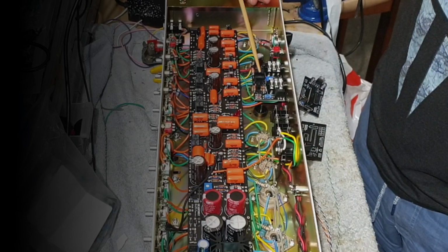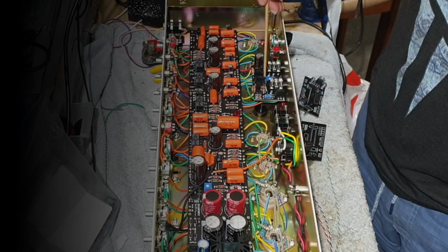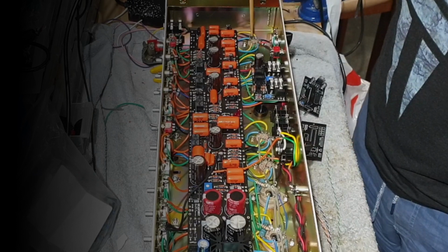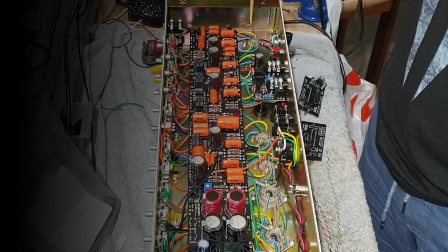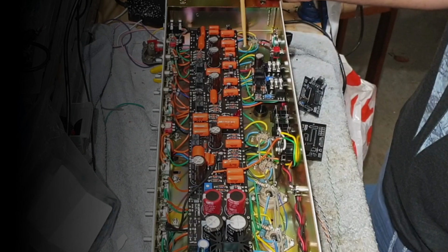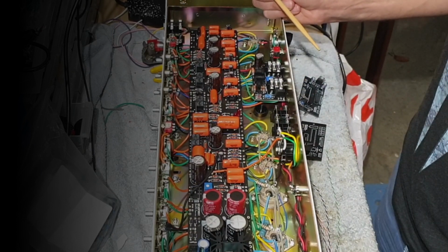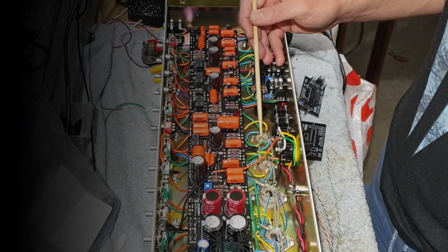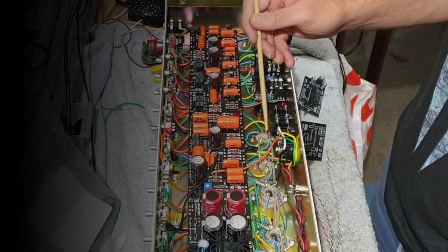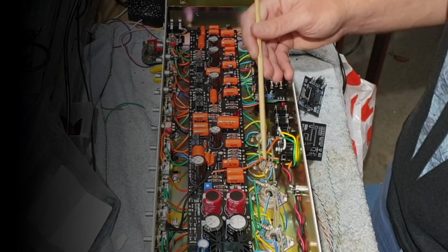So we're using our head first solid state metro loop here on this one. And I've got the first 3 preamp tubes on DC heaters because you tend to pick up noise in the amp first through the first few gain stages. The later gain stages, not so sensitive. So the phase inverter and this last gain stage here for the lead channel is wired as normal AC heaters.